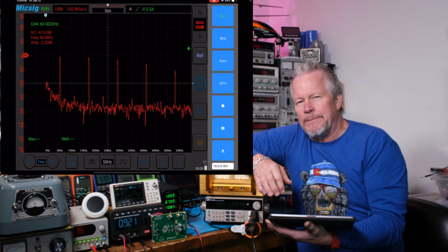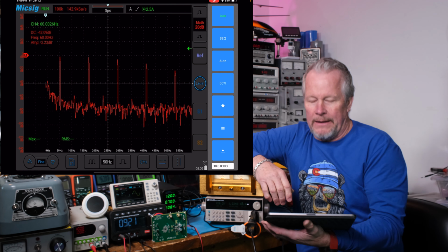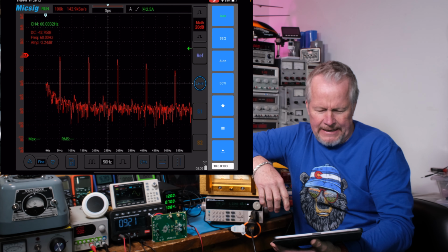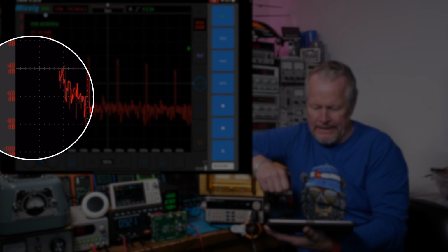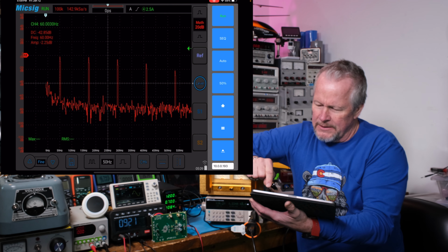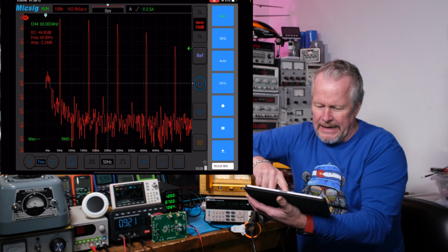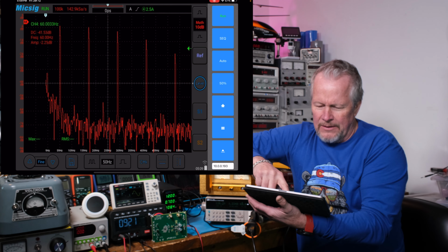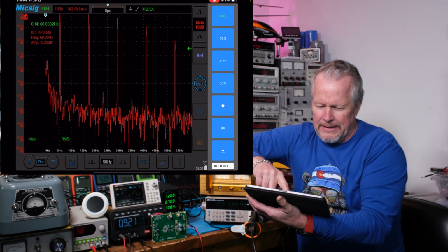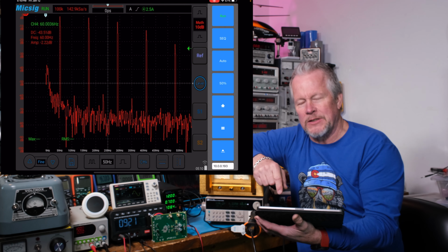So, these are 8-bit scopes, right? So you can't get really deep depth like 100 dB. I mean, the noise floor on this looks like it's, what, like 60 dB? 80 dB is trying to get down to 80. But if you look really close, I'm going to try to spread it out a little bit more. Okay, I'm spreading it out. See those? Okay, I'll put the 0 dB right at the top of the screen. Okay, so 0 dB is the top grid of the screen.